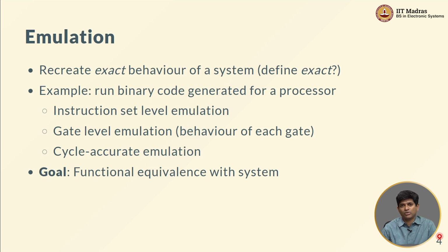An example of that would be, let's say I have a CPU core that I have designed. I have some kind of peripherals, maybe it's a UART, there's a timer, there's some kind of video display unit, right? A few different peripherals that can be attached to this particular CPU. And I then want to be able to emulate the behavior of this entire system. What do I mean by emulate? I should be able to run at the instruction set level, meaning that each individual instruction that would normally be executed by the processor, I should be able to execute on my emulated model as well and get the same behavior, right?